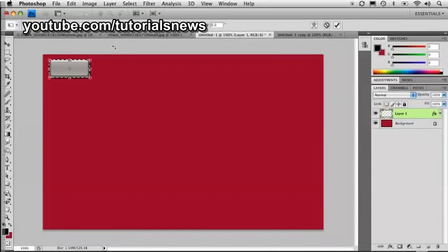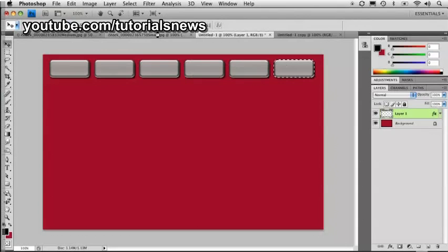I'm going to press Option Command T. That would be Alt Control T on a Windows, and that'll set us up for the step and repeat. So I'm going to drag this over, hold the Shift key down to constrain left or right movement, and drag this over until it gets a little bit of space in between them. I'm going to press Enter. Now, keeping it still selected, I'm going to press Shift Option Command, that'd be Shift Alt Control, and then press T a few more times, until we get across the document, just like you see there.